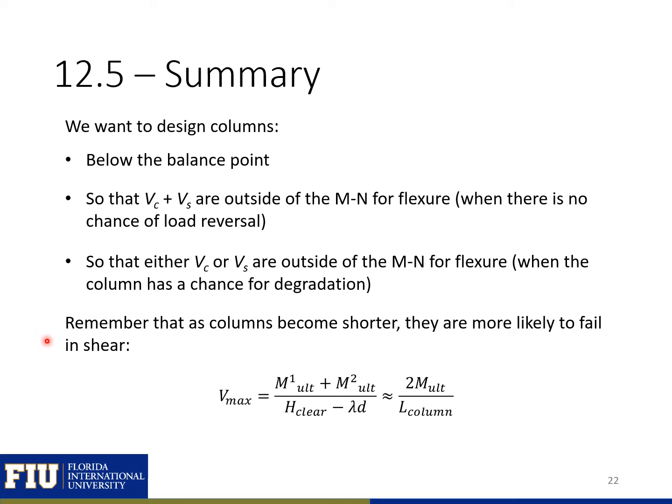And the last design principle to highlight is that as columns become shorter, they're more likely to fail in shear. So you can see our shear is inversely proportional to our column length. So a shorter column means a higher shear demand.